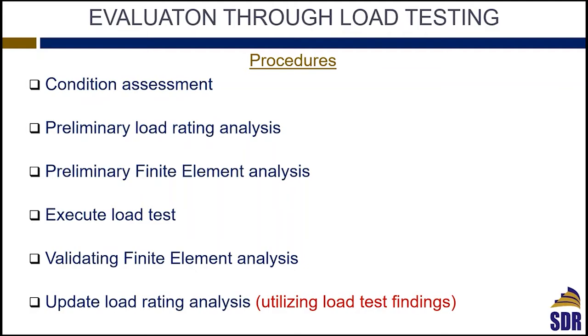Here at SDR, we do this structure evaluation process. We have developed our procedures based on our extended experience in this area of bridge engineering. We do a condition assessment, and after that we do our preliminary load rating analysis to determine what the deficient members are. Is it the main girder, the floor beam, the stringers, the slab approach span?